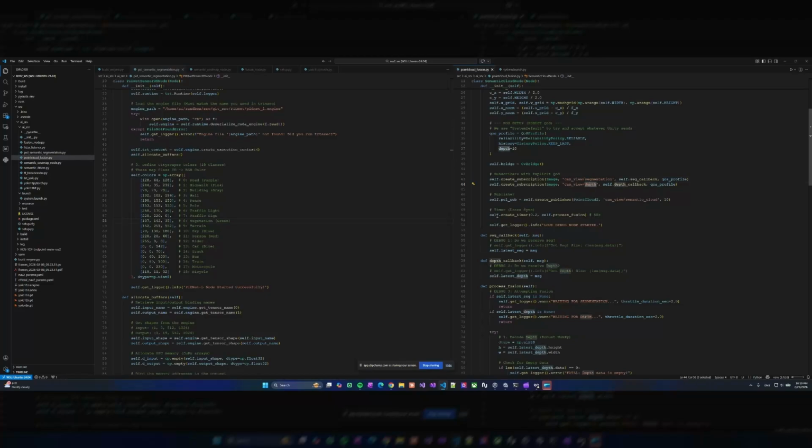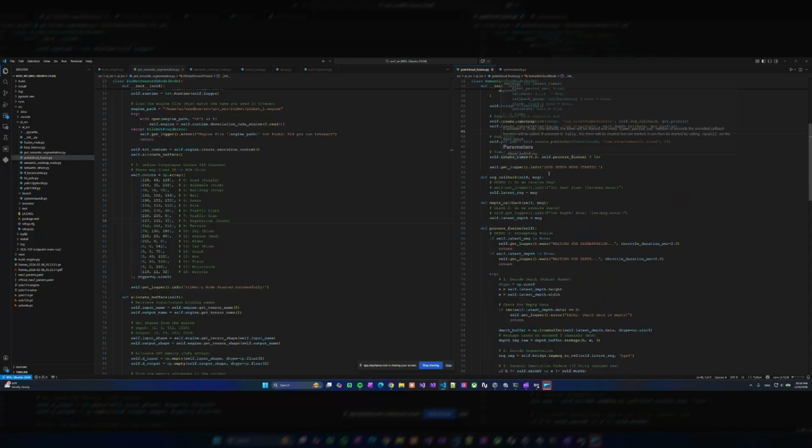Okay, since we know the color of the pixel, we know what area it belongs to, such as road or tree, things like that. Using the depth value, we can convert the pixel color into a 3D coordinate value, and that's how we generate the point clouds. All right, the point clouds that you saw in RViz were generated using this ROS node code here.